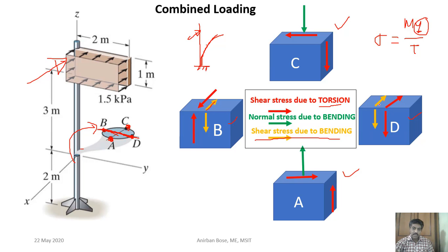So you can see at point P you will definitely get this kind of a shear. That is quite clear because it is trying to move in that direction. Then definitely shear will be in that direction. That is why you see at both B and D, the shear will be in this direction, and definitely to counterbalance that, the shear on the opposite faces will be in this direction.